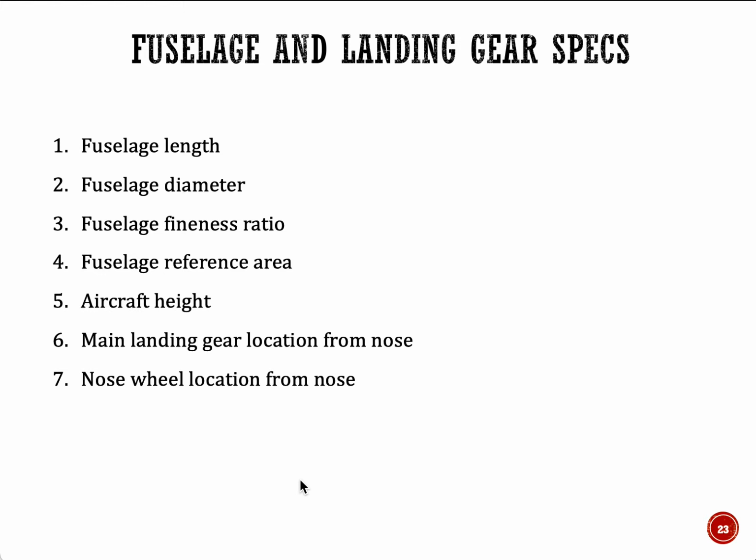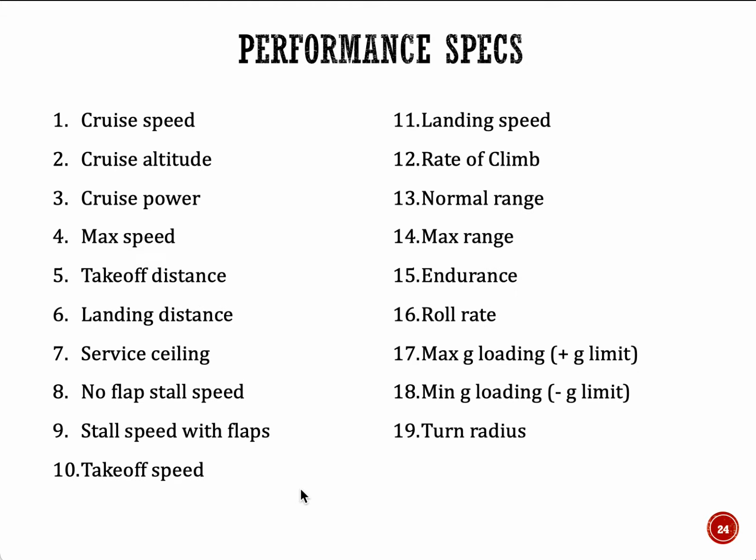One of the most important aspects of collecting a specification is basically the performance, because performance will let you set the requirements as well. Okay, so basically you got to look at cruise speed, cruise altitude, cruise power, max speed, takeoff distance, landing distance, service ceiling, no flap stall speed, stall speed with flaps, takeoff speed, landing speed, rate of climb, normal range, max range, endurance, roll rate, max G loading, min G loading, turn radius, etc.